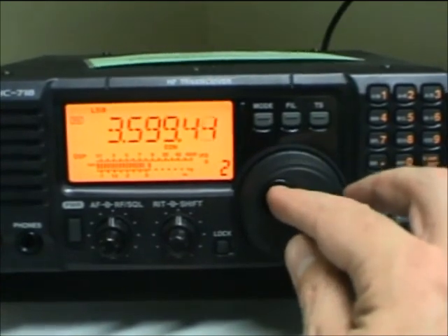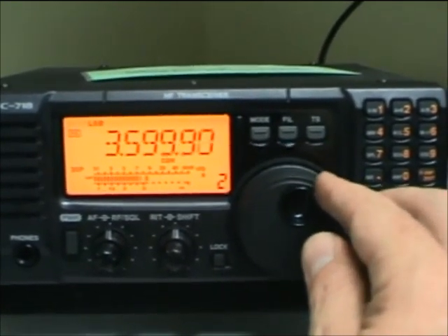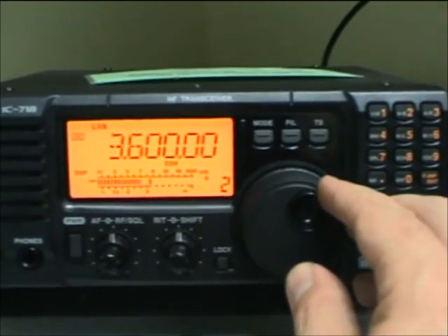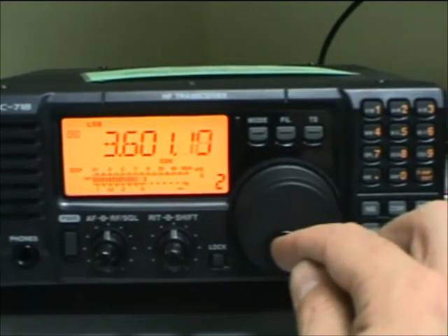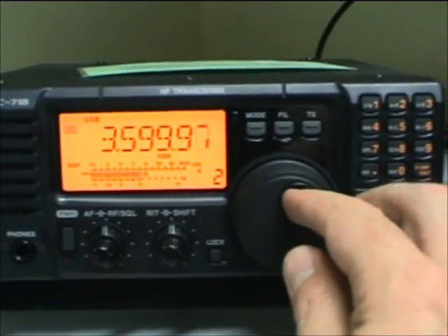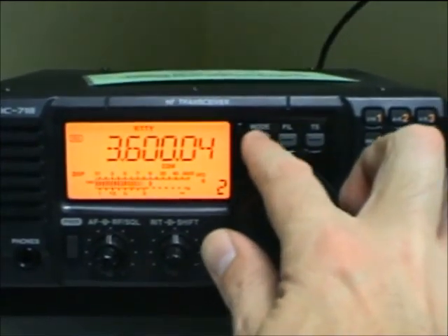So it's not until we've got it tuned on the correct frequency of single sideband that all the tones in the voice are the correct frequency. You get that monkey chatter effect. Now with AM, you don't have that problem. So we're just tuned there.